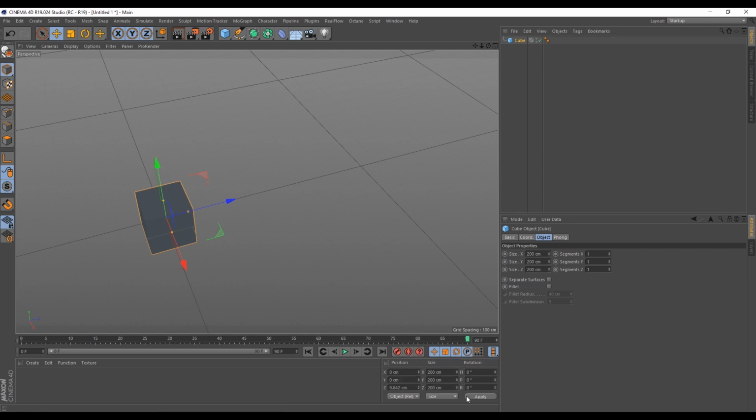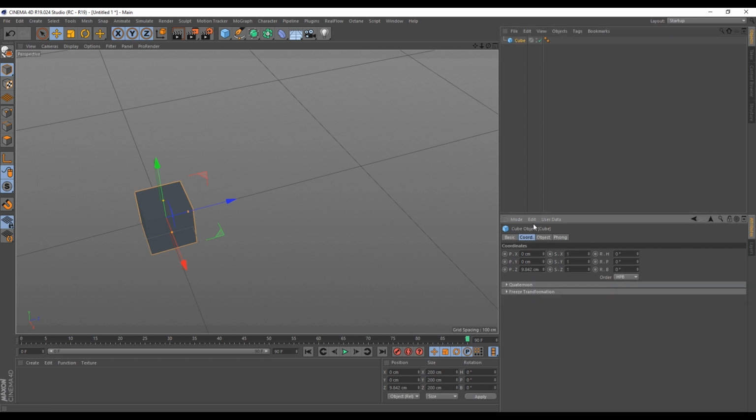So our next keyword was our attributes or properties, and this is our attribute panel here in Cinema4D. So selecting this cube, these are the attributes of the cube, and if I go to the coordinates, that's where we find what we want to work with. So we want to animate the position on the z-axis. So this is the position we want. So if I just click and drag this, you see that it moves only on the z-axis.